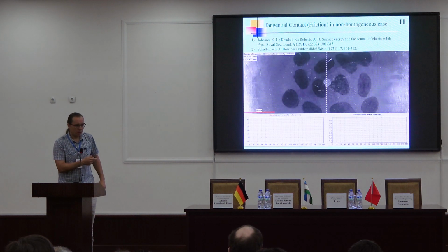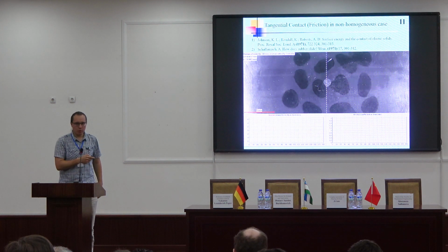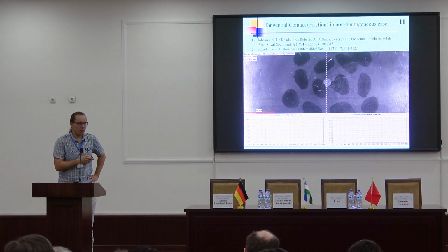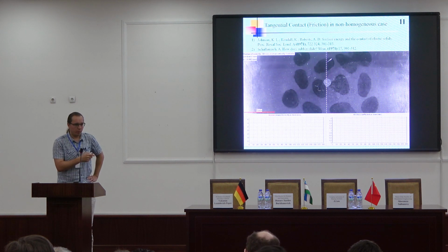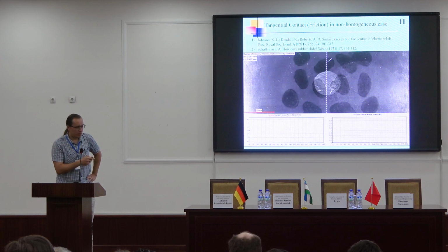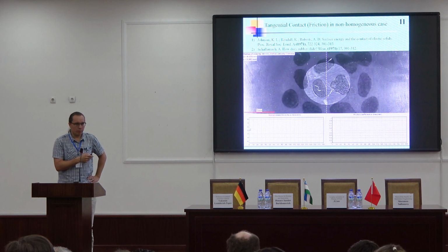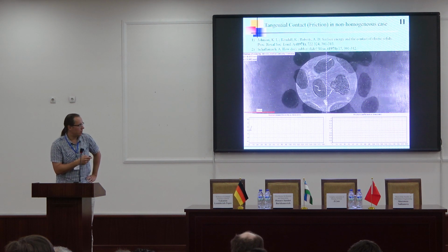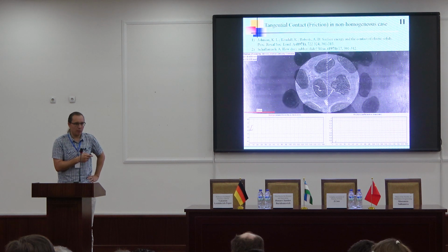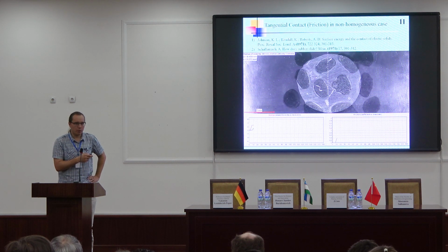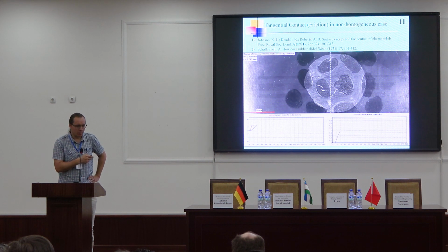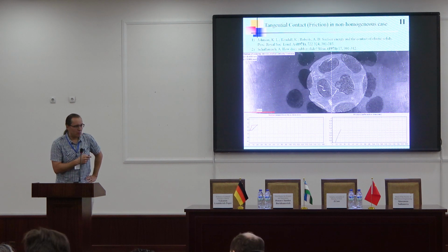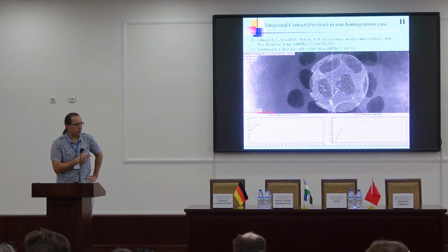And the last slide is the tangential motion of the indenter. Here, after indentation to some critical depth, we performed motion of the indenter with very small velocity, 1 micrometer per second. You can see here the black spots. Black spots are areas of the indenter after chemical treatment, which show much bigger adhesive work, adhesive strengths. It's a chemically non-homogeneous system.